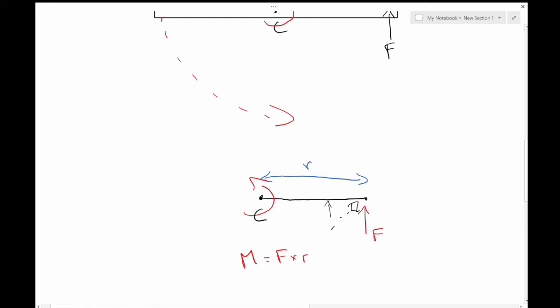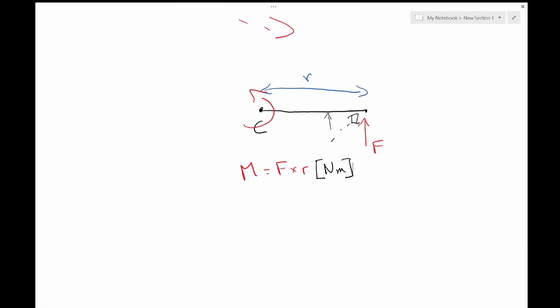And the moment here is going to give us units of Newton meters, which I've always found kind of confusing, because if you've taken some physics, you'll know that Newton meters is also the unit for energy, joules. And it seems weird that we'd be talking about this rotational force, but it's measured in joules. We can get around that through an explanation that I quite like, which is that Newton meters isn't really strictly correct. The rotational force is actually measured in Newton meters per radian.